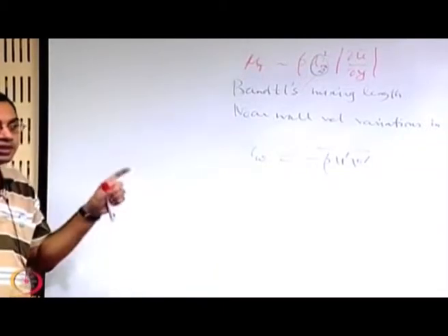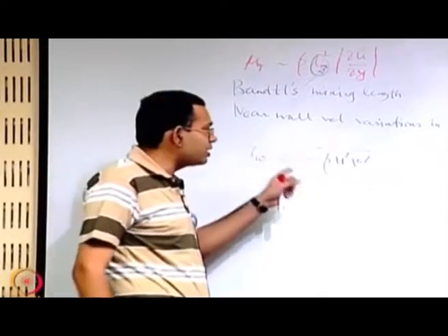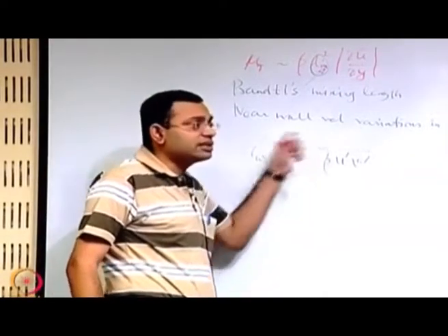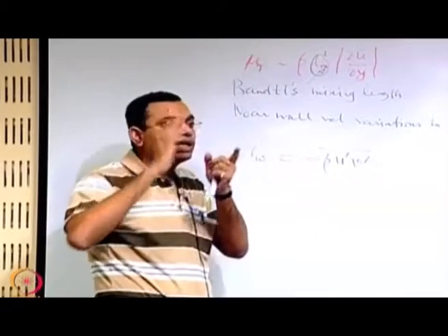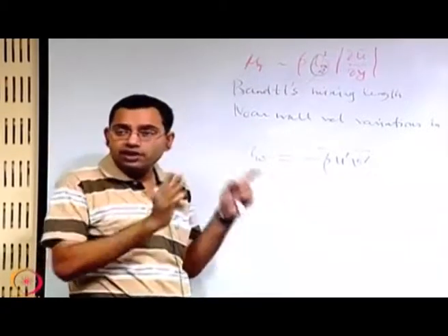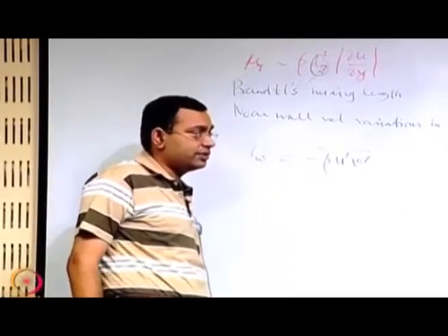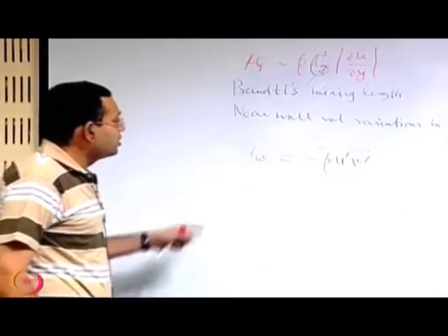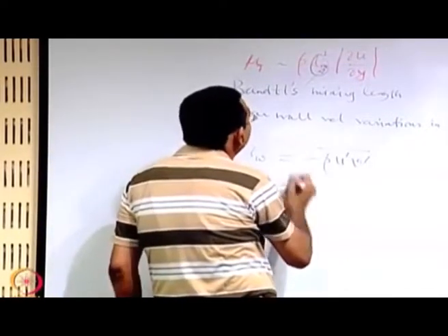That is the physical understanding behind this equation. So writing an equation is not important. This is not a universal equation, we are writing it at a location for a transition by keeping certain physical constraints in mind, and it is important to keep that physical argument in mind when we are writing this equation. Next, if you are now using the Prandtl's mixing length model,